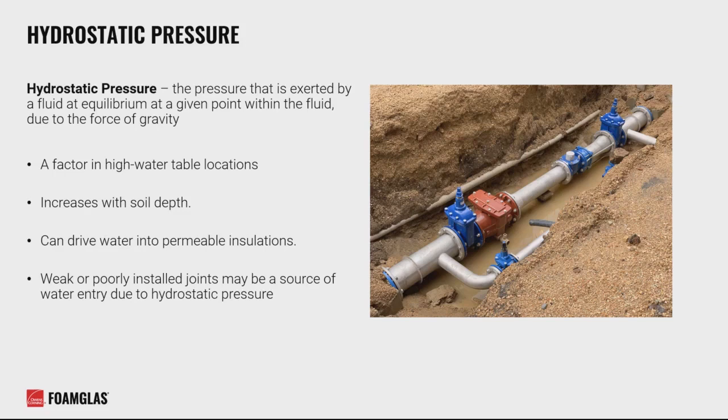The pressure generated can drive water into insulation systems via gaps or breaches of the system's moisture barrier, particularly at joints and protrusions. In the case of absorbent insulations, it can then seep in and saturate the insulation material, compromising thermal performance. In these areas, a closed cell and non-absorbent insulation material should be considered in order to mitigate the risk of insulation failure due to moisture ingress.